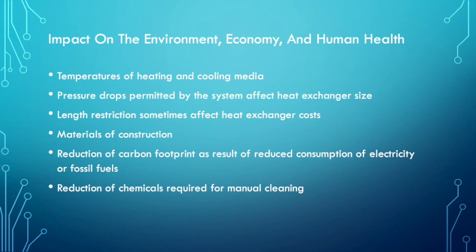The next point is that line length sometimes affects heat exchanger cost. However, there are many exceptions and limiting conditions, so we cannot simply say the longer the cheaper. Then there are the material of construction, corrosive tendency, and purity requirement of the fluid being handled.